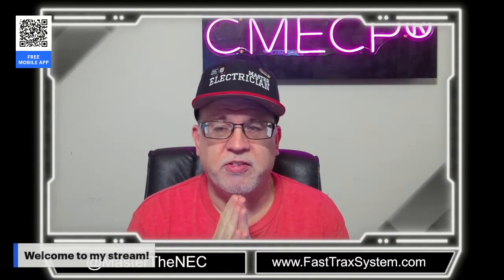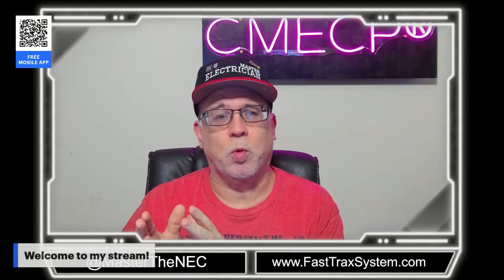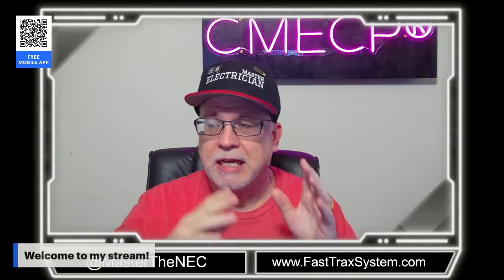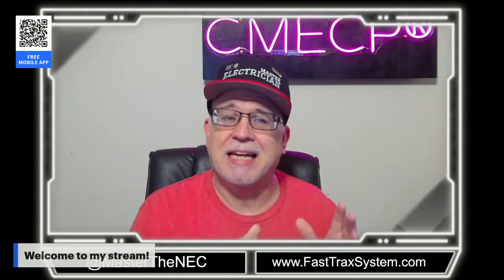Moral of the story, think about the generators you purchase and the application that you're using them for. If you are truly going to use it just for portable needs, right, then do me a favor. If that's the application you're going to be using it for, get a generator that has a bonded neutral and use it for those portable applications.